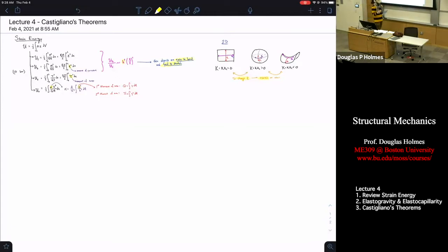However, if you can write down the energy of some deformation, so for instance, the energy to bend an object, and you can write down the energy that some force contributes to your object, say gravity acting on it, what you can typically do is ask the question, at what length scale, or in some problems, at what time scale, are these energies roughly the same? And what that tells you is if your length is larger than the length scale where these things are balanced, you're going to see one type of behavior. And if it's smaller, you're going to see a different type of behavior. What do I mean? Let's go back to our sheet.